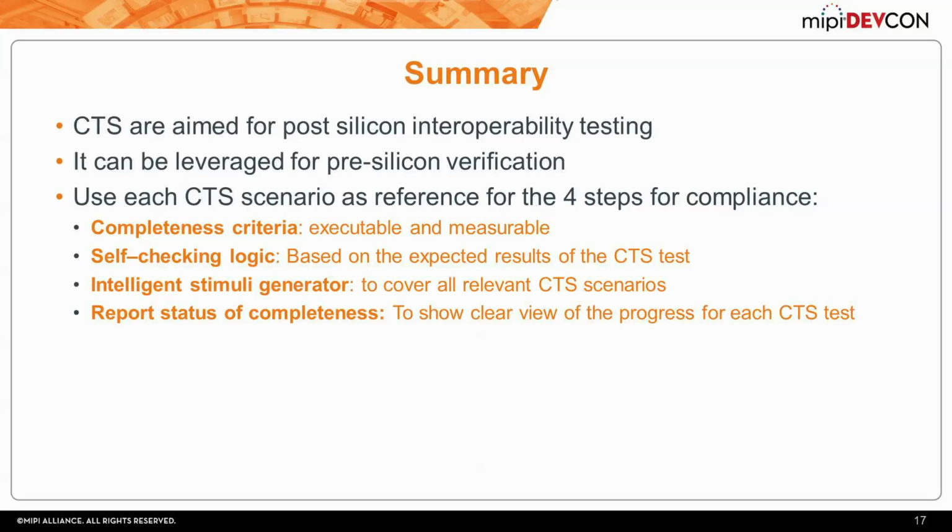So as I said, the CTS are aimed for post-silicon interoperability testing and not necessarily for verification. They are covering the main aspects of the spec, but not all. It can be leveraged for pre-silicon verification, but it's still not enough. You should still invest more in creating more complex scenarios, more error injections, more randomization, because not everything can be created in post-silicon, and it's easier in pre-silicon.